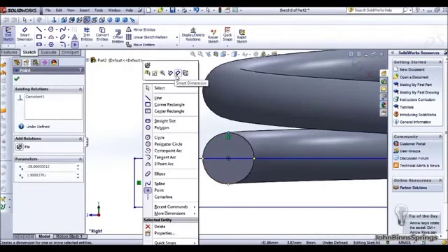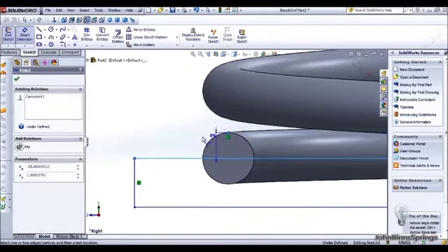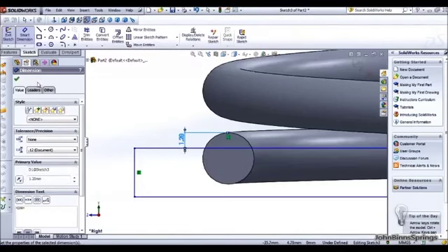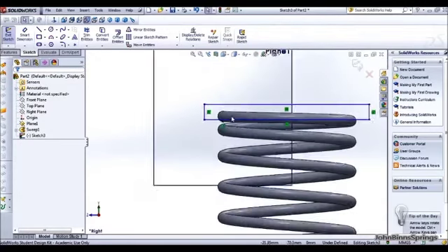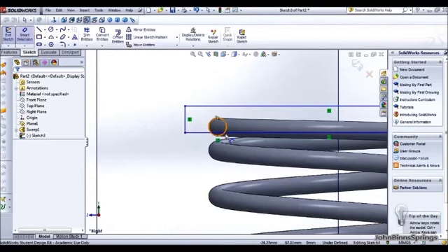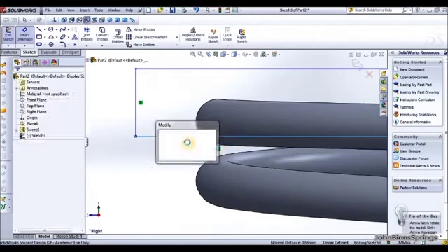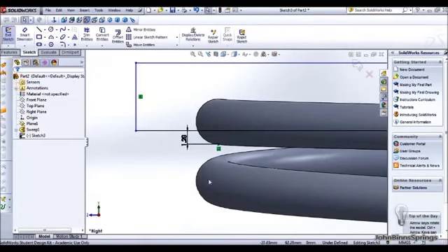Right click and then smart dimension. So that smart dimension that line to that line. At the moment it's at 50%. We want 70%. Between 70 and 75% is okay. So just put the 1.2 mil in. Tick that. And we'll do that again at the same at the top. 1.2 again. Enter that. Tick that.